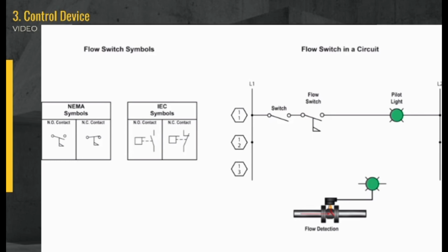There are many different types of flow switches, but the working principle is quite the same. The majority of them have a paddle or magnetic trigger of some sort, which is connected to a circuit and placed through the channel where the substance will be passing through. The paddle is rotated by whatever substance is passing through and sends a signal back to a transducer. The transducer takes the signal and passes it to a transmitter. The transmitter measures this reading against a predefined set of parameters and performs whatever signal or action is required to adjust the behavior of components and mechanisms.